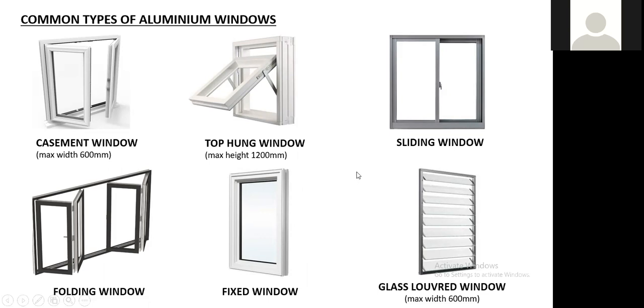Okay, so it's not that simple, which one do you want to use. It's not that straightforward. For top hung windows, of course, we use them for toilets and places where you need a bit more privacy. But of course, there could be main windows that use top hung windows also. But it needs to be restricted to 10 degrees or 10 cm opening for safety purposes. Okay, but the ventilation is very limited. So if you want to ventilate the space, casement window might be the better option.